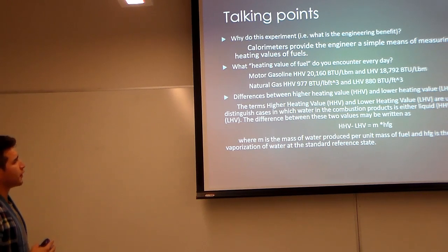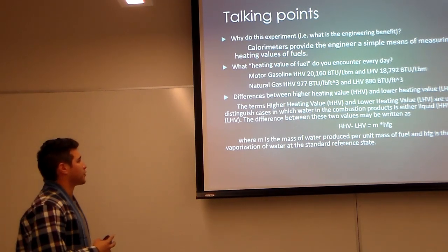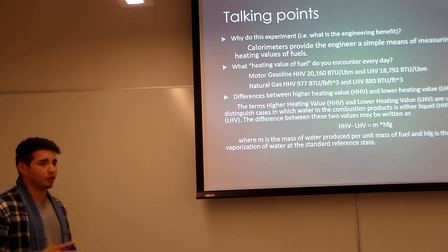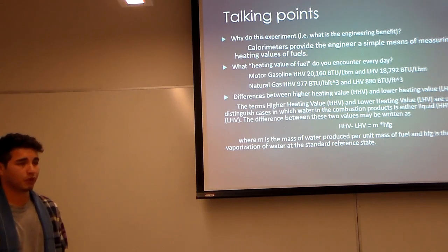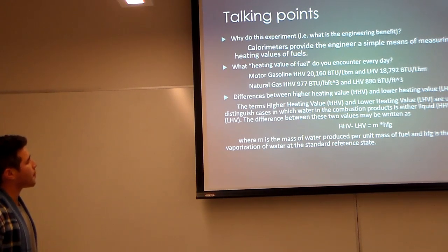So why do this experiment? Calorimeters provide an engineered, simple means of measuring the heating value of fuels. In our example, we'll be doing one version where we know the heating value and a second version where we don't know the heating value of the fuel that we are using.